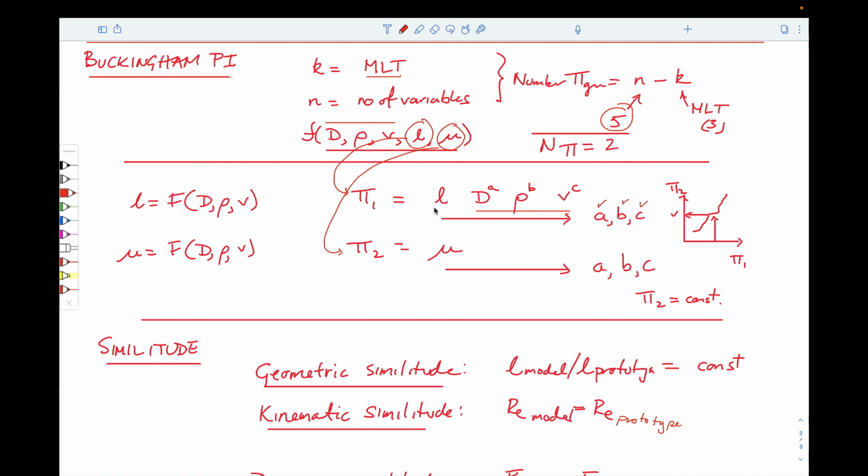We can substitute it back into this expression, and we'll end up with a non-dimensional variable. And this would typically be either Euler number or Reynolds number. If we do the second dimensionless group, then we'd use the next parameter. We'd tack that on here. Again, we'd use diameter, density, and velocity raised to these powers.